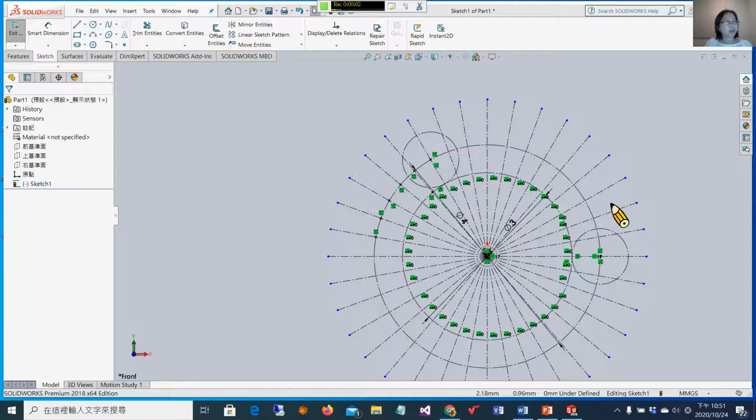During the rise and return regions, the roller leaves an amount from the prime circle. For example, at the cam angle 113 degrees, we have the displacement equal to 0.0536 inches.